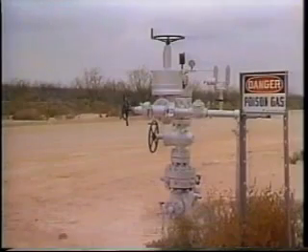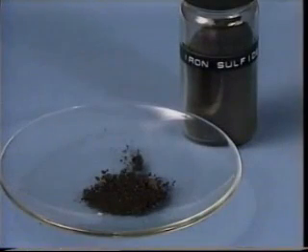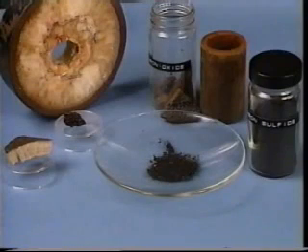Additives such as sequestering agents can control this problem. A problem that cannot be controlled occurs in sour gas areas, where iron sulfide can react with HCl to form a very corrosive product that can damage the tubulars. This and other problems reinforce the need for acid formation solubility testing before the job.